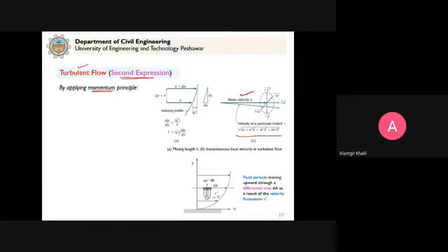This is how it essentially becomes three-dimensional. This velocity u has a fluctuation denoted by u dash, and it can be plus u dash or minus u dash, as we earlier saw in the diagram. It can also have fluctuation in the y direction, plus v dash and minus v dash. When you see a bar, it means we are averaging those fluctuations over a long period of time.